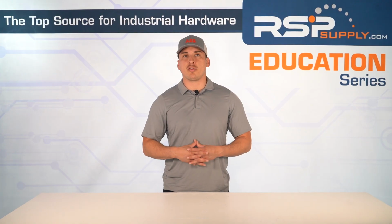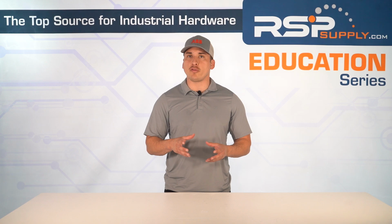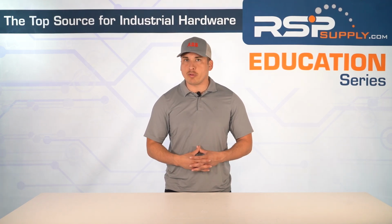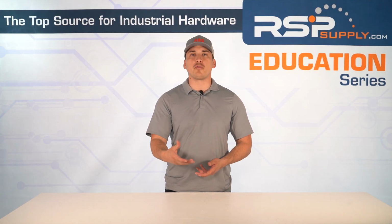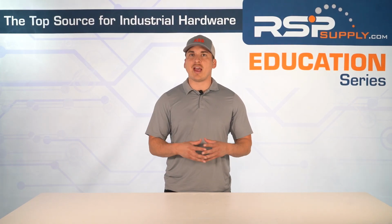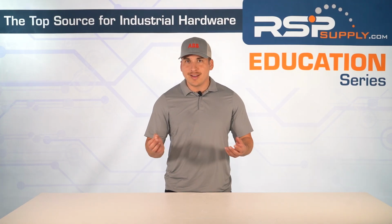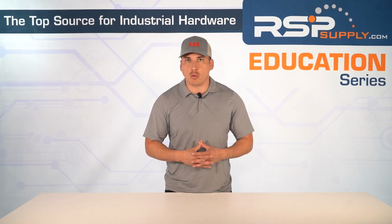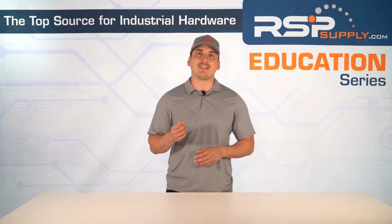So what are industrial sensors? They're specialized devices that are designed to detect and measure physical changes in the environment or in a machine. These changes might include temperature or pressure or distance, maybe light or motion or fluid flow, or even the presence of a specific object or a material. Once detected, though, the sensor is going to convert this physical input into an electrical signal. This signal can then be used by a control system, like a programmable logic controller or a computer, to monitor conditions or trigger specific responses in a process.